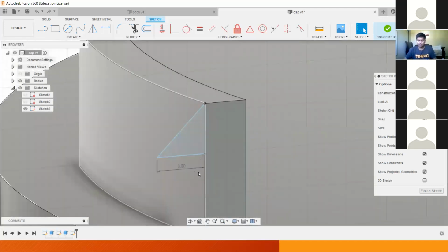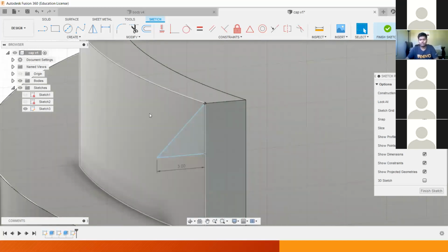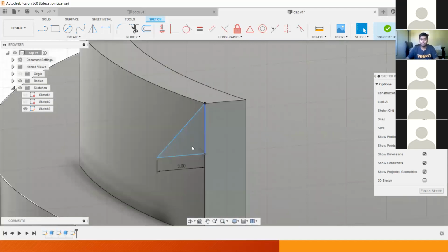All right, so this side should be 5 millimeters and this side should be 3 millimeters. And to finish it off, we're going to connect the top and bottom of the triangle, so that when my mouse hovers over this area, we have this triangle fully highlighted. When it's highlighted like this, that means this area is extrudable. So this area we can extrude, this area we can extrude, and most importantly, this area we can also extrude.